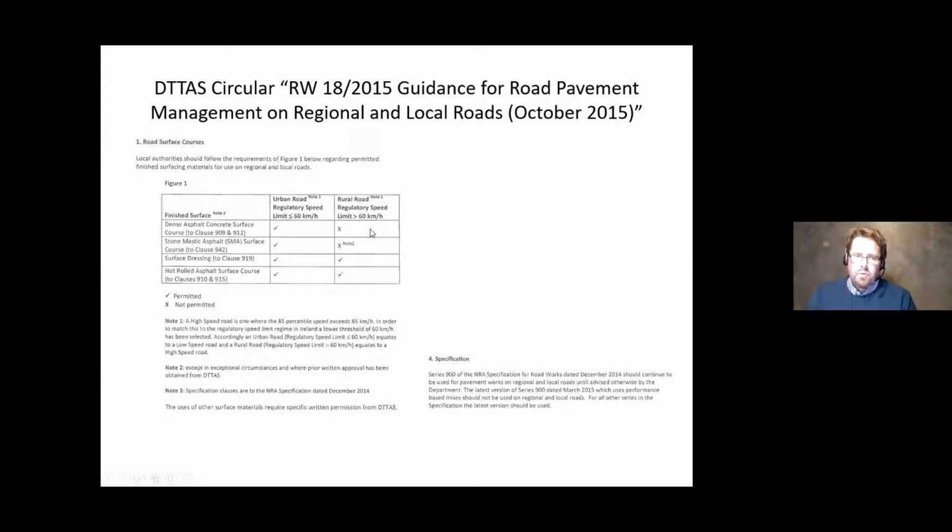And if you're in a rural road or a very low volume national primary or national secondary, is SMA going to be beneficial? Are you going to have enough traffic to wear off the surfacing to get the grip out of it? Could it be a hindrance to you more than a help? So just weigh up the options there, but be conscious if you're working on local roads of this road note. And I'd like to thank Alan Lynch from ARUP for bringing this to my attention last year, because it's something I would have missed completely otherwise.